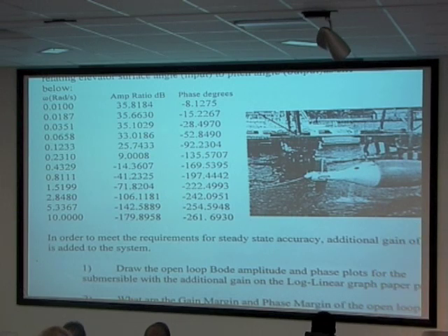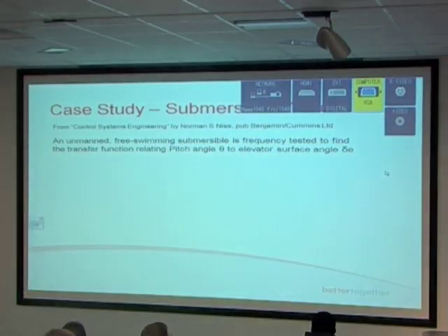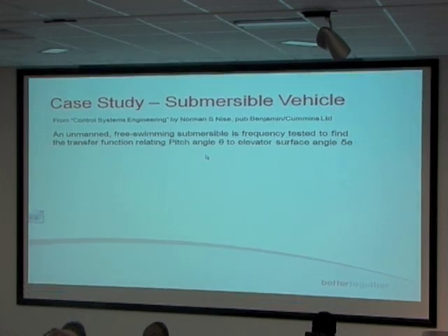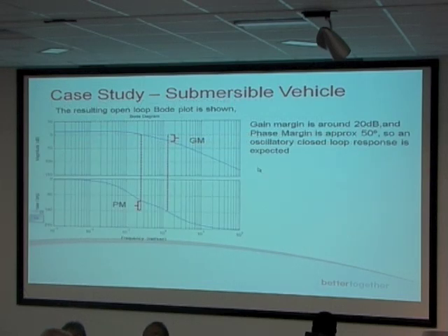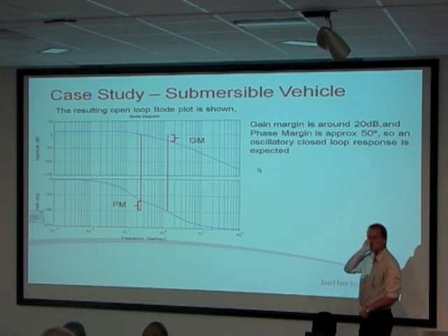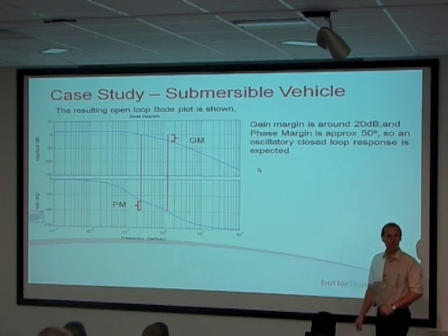Why am I interested in that? Well, fairly obviously, what I'm looking at is the output, which is the pitch angle of the vehicle, theta, to the elevator surface angle, delta E. From that experimental data, I can construct an open loop Bode plot and have a quick look at the gain and phase margins.